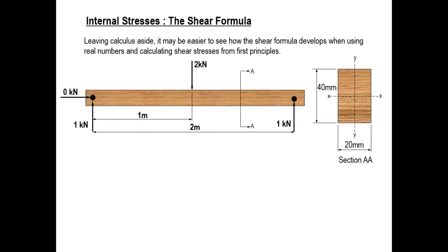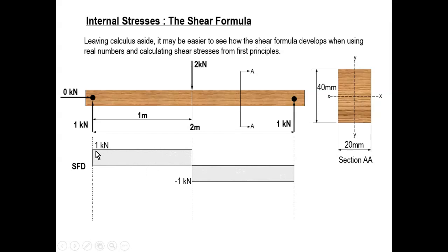All right, so now we can do this for a simple beam which is simply supported. If you apply 2 kilonewton, that's symmetric. You know that this load would be half at the reactions, and then you plot the shear force diagram. Everywhere is maximum. So the maximum value of V is 1 kilonewton. All right. Then that is the cross section. So you know the maximum V.